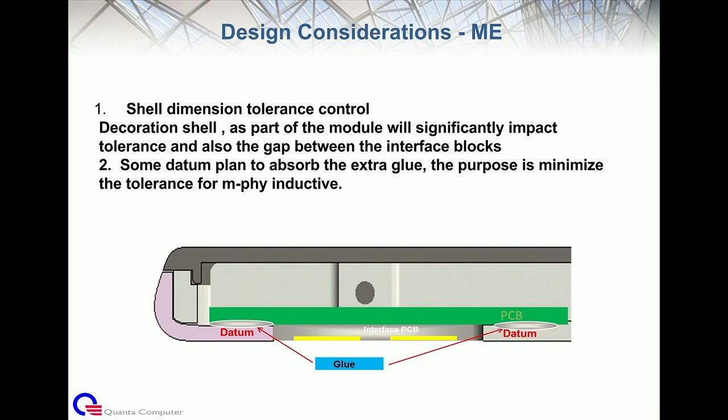So here is the most important design consideration for mechanical, which I think we need to highlight. Everybody knows that UniPro is the core of the Ara structure. So the performance and stability of the UniPro bus is the most important thing for this platform. No matter if it will be spring type or contact type, the tolerance between the interface block of the module and the interface block of the endo needs to be very well controlled to guarantee the functionality and the performance.